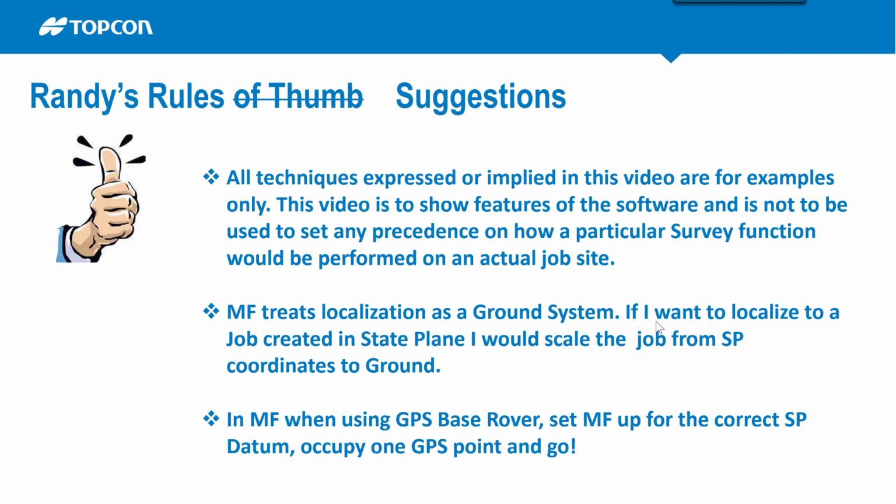If I wanted to work with a job that was created in state plane, in my AutoCAD, I would scale that job from state plane to a ground system, send it out to the data collector, and I would localize that way. Then if I measure between GPS and ground, I'd be good either way. But unfortunately, a lot of the jobs that you run into are designed in state plane,